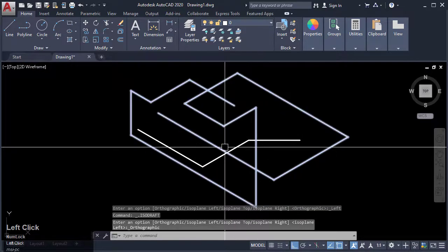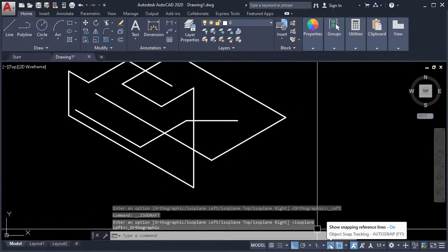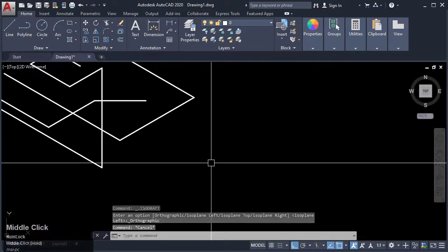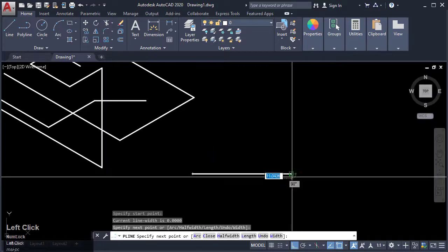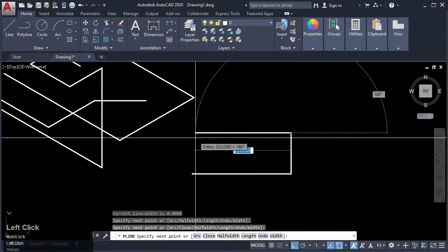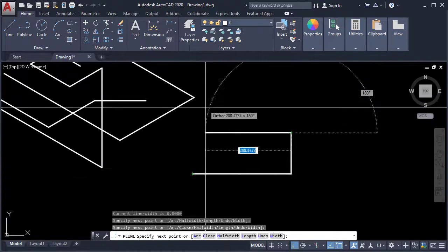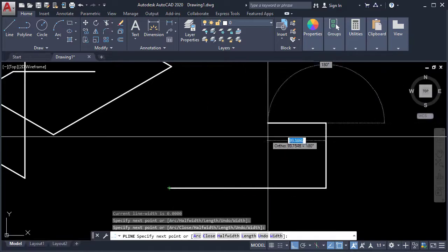original cursor orientation. Now in here, this one is your snapping of reference lines. Let's demonstrate how that works. So let's say I have in here a line, and I wish now to extend that line without typing the distance, and I want that line to reach towards this location.